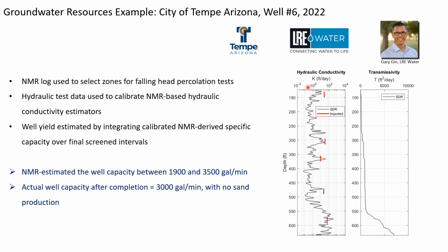And after that, the NMR estimated hydraulic conductivity plot was used to estimate NMR-derived specific capacity over final screened intervals. And it turned out that actually the NMR estimated well capacity was correlated really nicely with the actual well capacity after completion, as can be seen here.